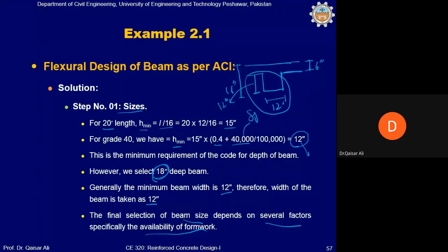The beam depth provided shall be at least 3 times the thickness of the slab. So an 18 inch deep beam is also satisfying that criteria. Clear?